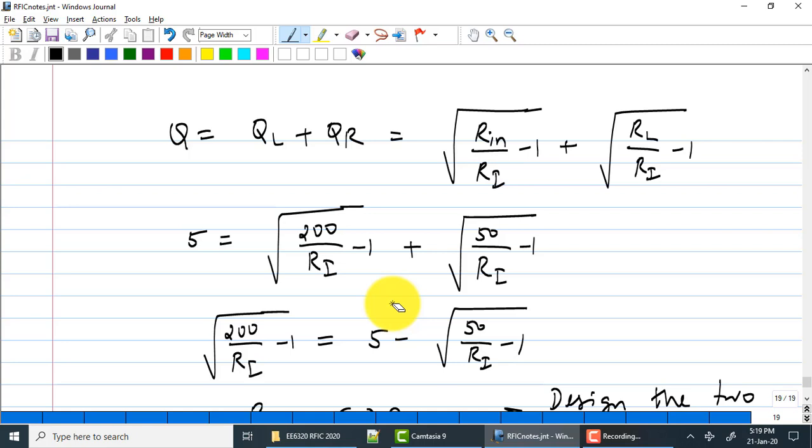How do you wind it around air? You don't have a 3D. You cannot make a solenoid, right, or any of those 3D shapes. Okay, so what you can do is planar concentric rings can be made. Okay, which is what you do, and we will discuss that separately in a separate class much later on in the course. You don't need it right now. Okay, maybe in a couple of classes I'll come back to it. Okay, so there are fundamental limits on the Q that you can achieve.